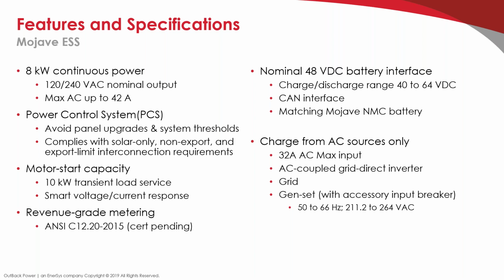Yeah, effectively it's based on the battery state of charge, as well as other loads that are present. So if the battery is fully charged and shuts down the inverter, and then you activate some other fairly large load in the home, remember, it takes 5 minutes for that grid tie inverter to come back on anyway. So it'll initiate that as soon as it sees that there's a place for that power to go.